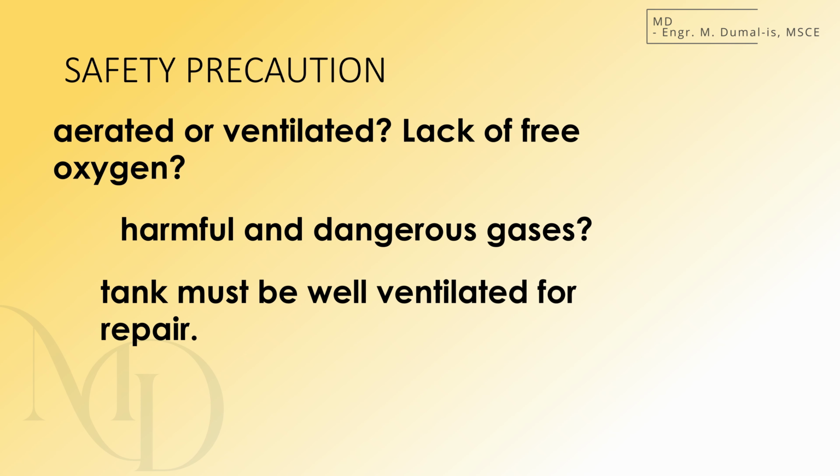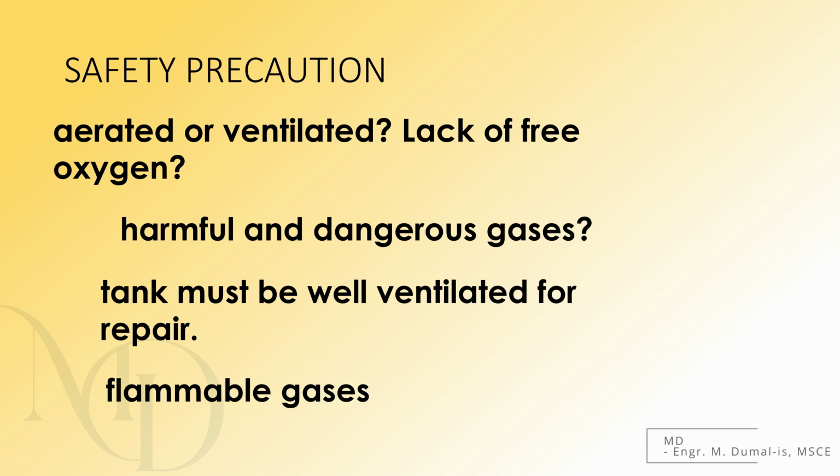One safe practice is to remove the manhole cover a few days in advance of the work. Another precaution is to supply fresh air inside the tank while the work is being done. We must also remember that septic tanks can contain flammable gases, which may ignite and cause a violent explosion. If lighting is needed inside the tank, only an electric emergency lamp with a properly insulated cord should be used. In the absence of an electric source, a flashlight powered by a dry cell battery is a safe alternative.